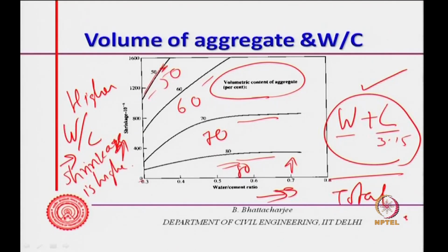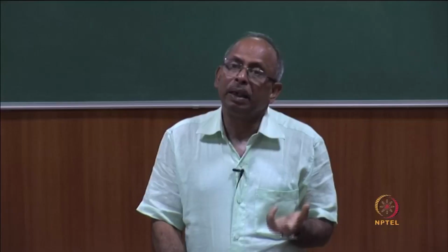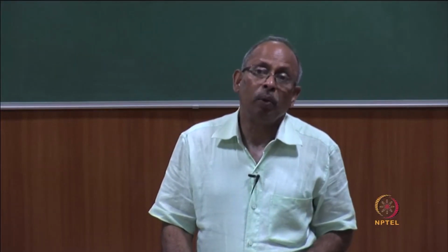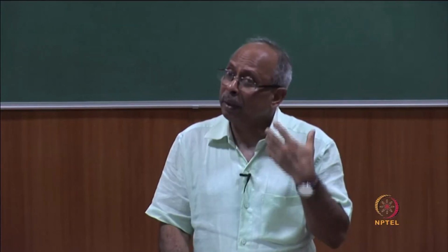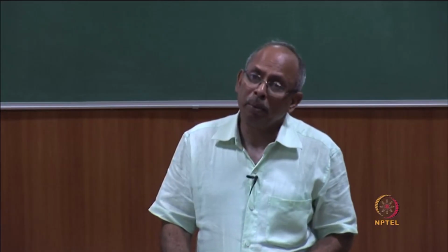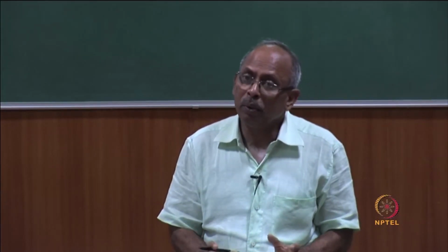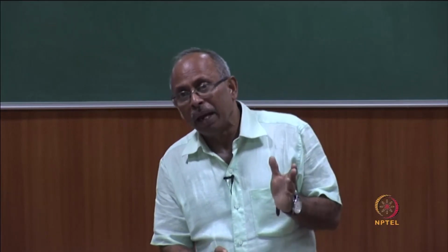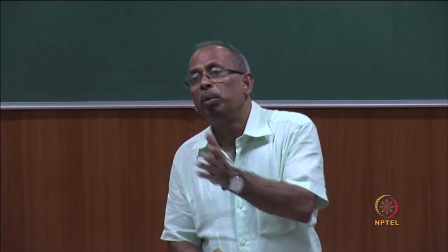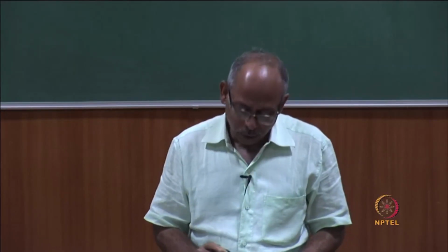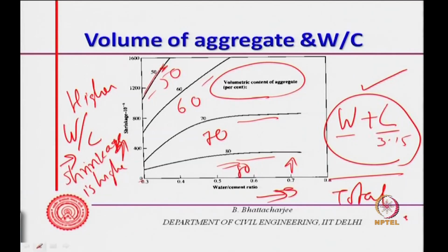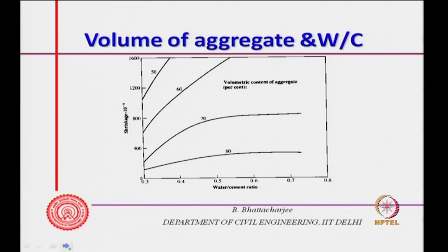So, for a given paste content, shrinkage increases with water cement ratio, because with a large amount of capillary pores, more drying is possible, more water may move out, and even with larger capillaries, the scope of emptying the gel pore or interlayer water movement in the capillary space is now more. So, this is related to those aspects.